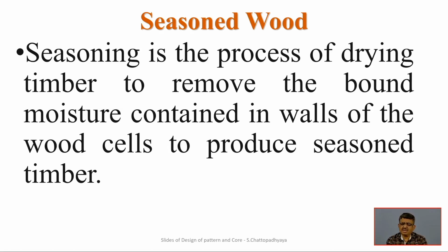Because the moisture will dry up over a long duration, and whenever it dries up, the wood will have dimensional distortion, and that is the last thing casting people want. So dimensional distortion has to be minimum, and that is why seasoned wood has to be used. Seasoning can be natural, putting the wood in the heat and dust in the open for quite some time, so that the water molecules present in the intricate microstructures dry up. That is known as natural seasoning.